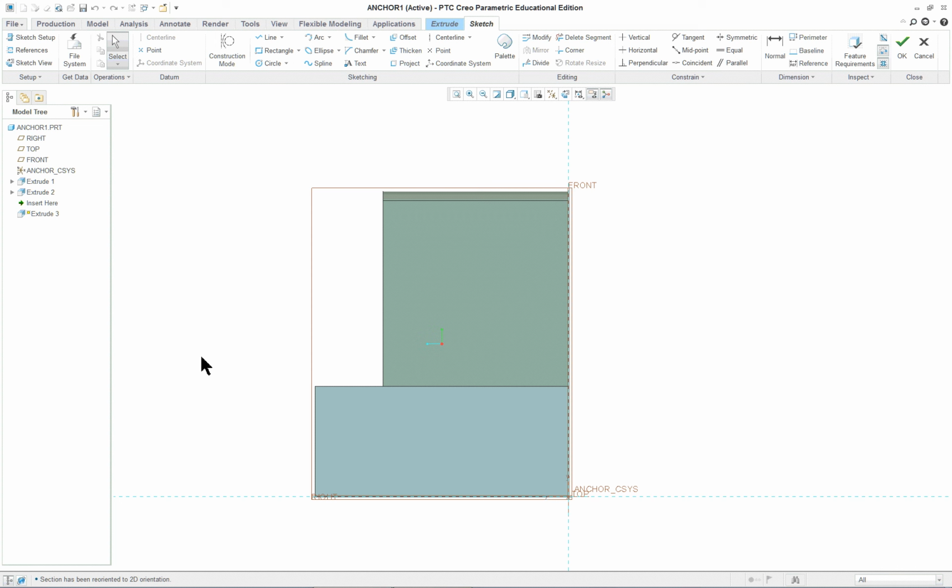This is the same thing. If you're a machinist, you're going to cut this out, then you're going to cut this out, or vice versa. You're not going to cut everything at the exact same time. Therefore, keep the features separate so that design intent has a little bit more integrity. If you want to come back and change this cut, why should you also have to deal with this one at the same time? So separate them always, under every circumstance.